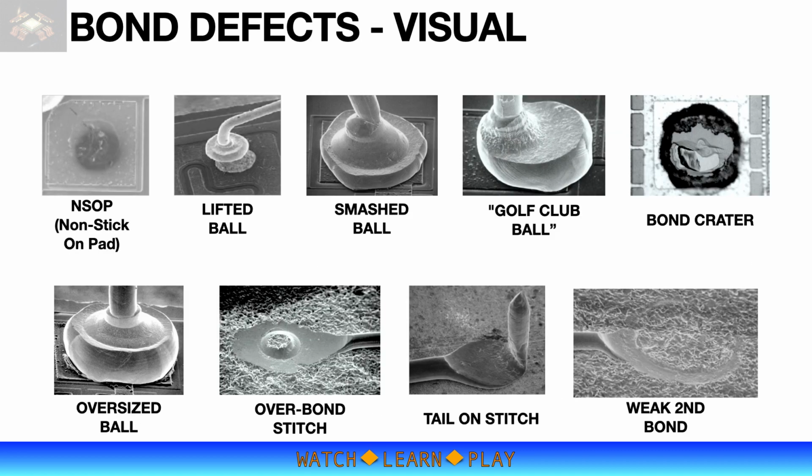Let's now talk about bond visual quality. Because the bonds or wires are really small, to see the bond quality, the device must be inspected under a microscope, usually at 10x to 40x magnification. To see details similar to images on this slide, a high magnification microscope is required with magnification of at least 50x to 100x, or even higher depending on the size of the bond.